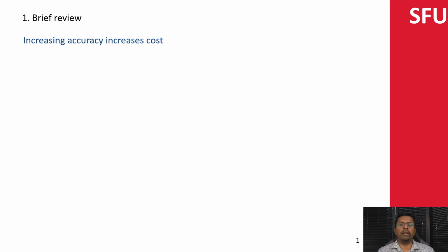But if you're looking at an assembly of a door, maybe you want to make sure that the door is smaller than the opening. You can always fit it, so you don't want it to be larger. So then you have a different tolerance trade-off that goes in here. Nonetheless, as designers, you would have an idea of what you actually want to do. Because you're not going to be manufacturing the part as well, and you don't want the manufacturer to constantly go back and look at all your notes about the application, what you would rather do is convey all of that information in a standard drawing format. So that's where the tolerancing comes in.